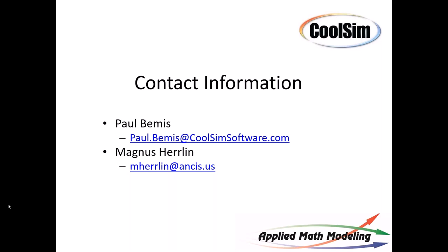The other thing about PUE is it's a point in time, and it changes. What you need is the average PUE over the year, because it's not constant. But yeah, you are right. If you change the cooling system to evaporative, or you add an economizer, it will change the PUE quite dramatically, compared to, in this case, leakage.